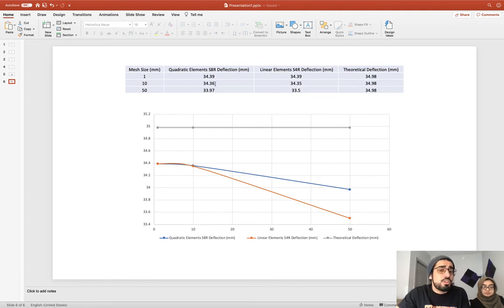And by the way, you're going to tell me why for quadratic elements we use 8 nodes, and for linear elements we use 4. This actually goes back to the theory of finite element. When you define the approximation functions, quadratic or linear, you need points to define the function over. For example, you know the equation of a straight line? Y equals ax plus b. You need 2 points to define the straight line, right? What's the equation of the quadratic? You need more points. That's why we need to use more nodes for the quadratic elements than the linear elements.